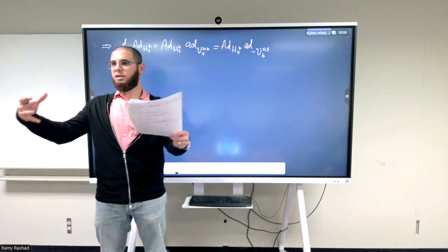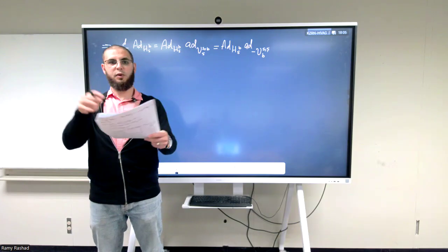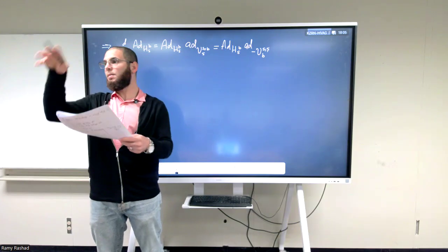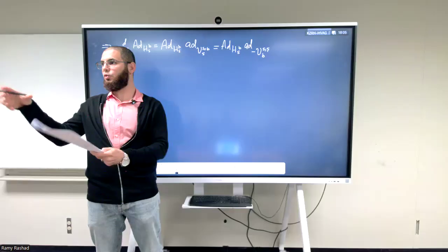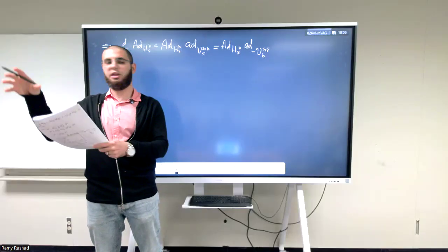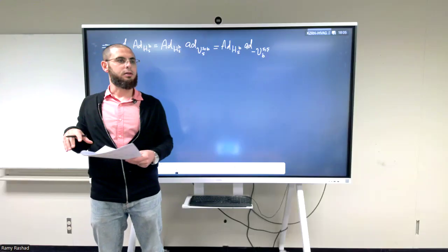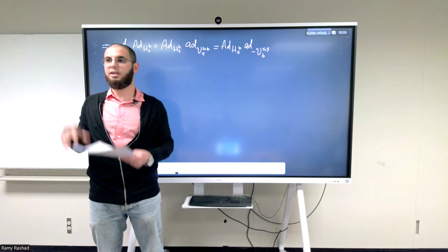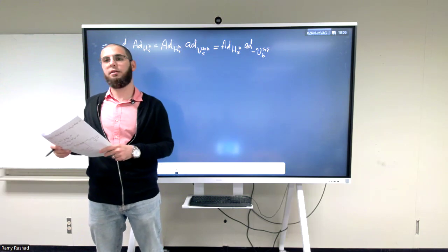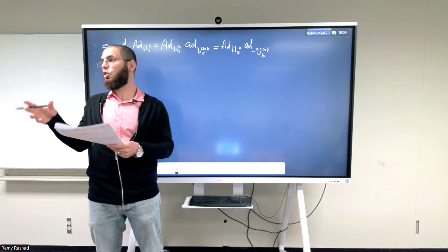You've seen how the adjoint looks, right? The adjoint itself consisted of just skew-symmetric matrices. You take the components of the twist, the linear part and the rotational part, and put them into skew-symmetric matrices. The skew-symmetric matrix is actually a linear operator.